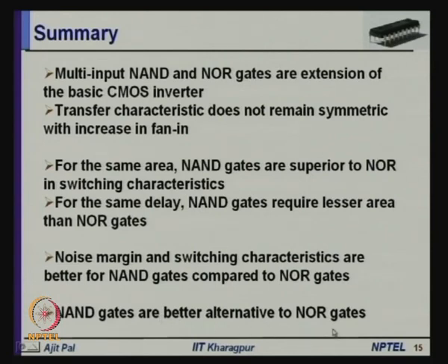So, although this is our conclusion, that by considering noise margin, delay characteristics and area, NAND gates are superior, in practice we shall be using both NAND and NOR gates together.